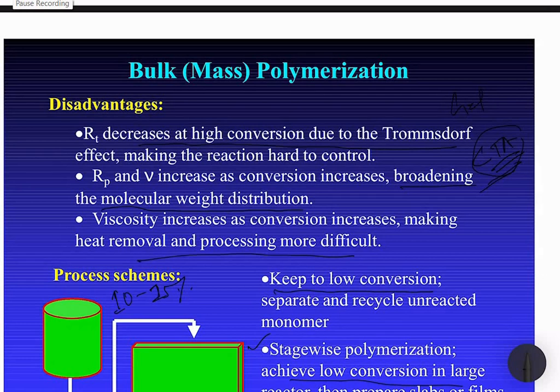Whereas in the initial phase, we had the fully grown polymers. So at the initial phase, maybe you have very high molecular weight polymers, and when the chain transfer agent is used after 1.5 hours or around 2 hours to resist the reaction from moving into the runaway mode, whatever chains were growing at that time were stopped.